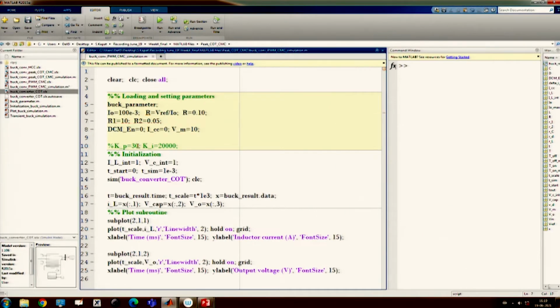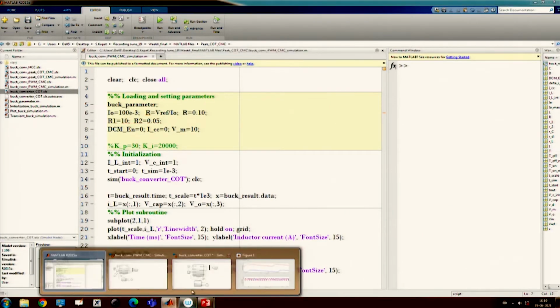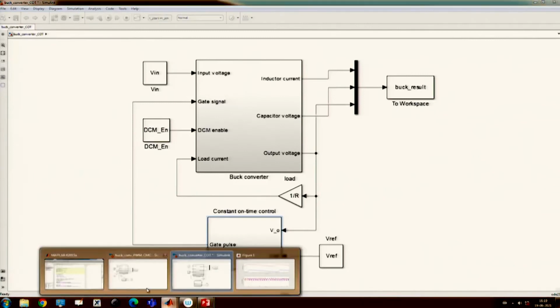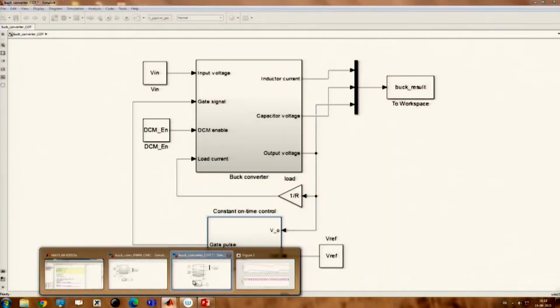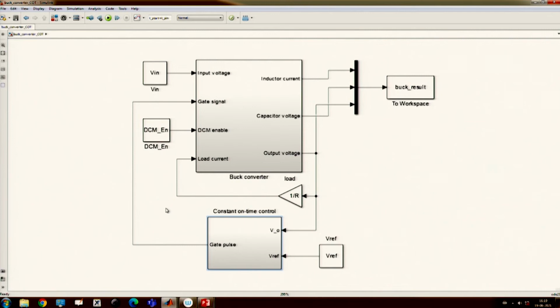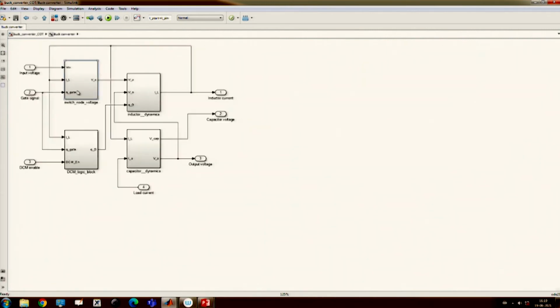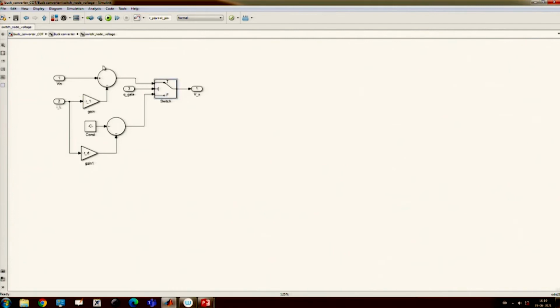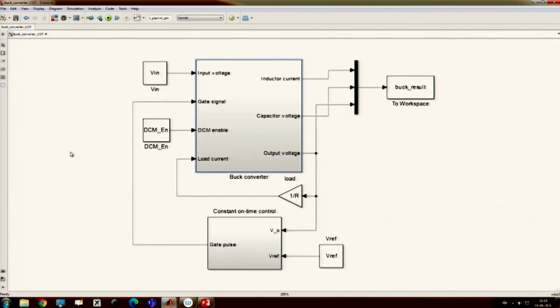And how can we make the load transient? There are multiple ways of doing a transient, but in this case we are going to take this way. We will introduce a switch, that means we already have some switch, so we will take one of the switches and introduce it here. This switch is my load resistance.